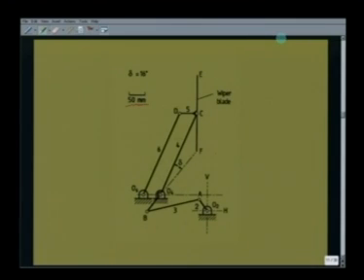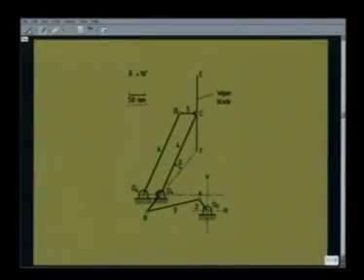The first part of the question is, what is the wiping field? That means, as this crank O2A is driven by a motor, what is the field that is wiped by this wiper blade? Now, to solve this problem, first we use a little bit of graphical method. We study only this 4-bar linkage, namely O2ABO4, and determine the extreme positions of this link O4B, that is link number 4. For that, we know, as usual, B is going along a circle with O4B as radius.